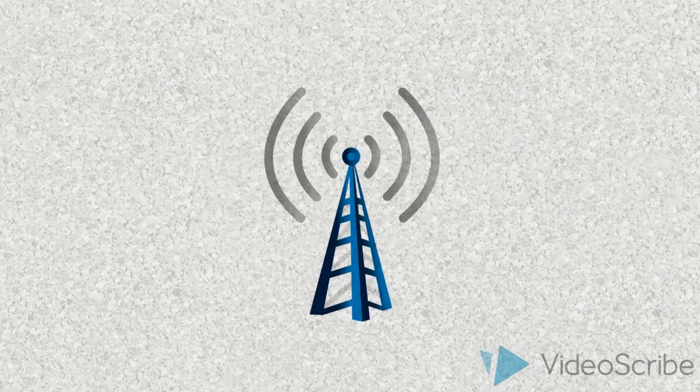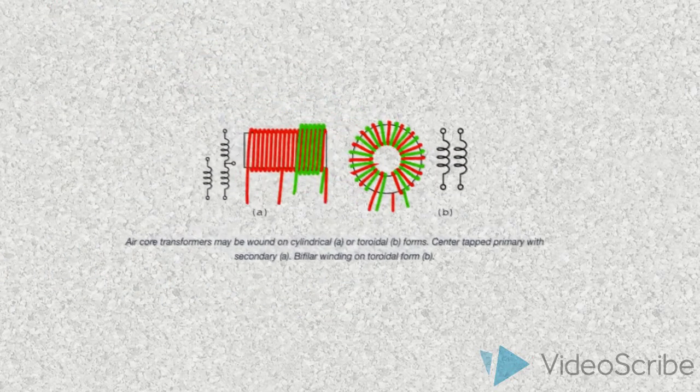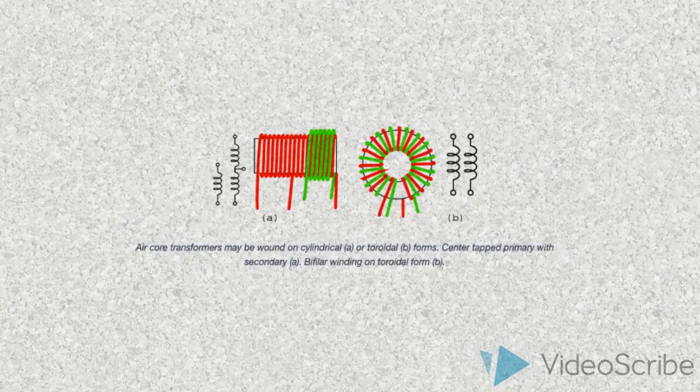Also, radio frequency circuits, which are needed for telecommunications, use air core transformers, as they have windings wrapped around a hollow tube, as the picture shows. Radio transformers have tapped windings, or two or more windings, designed to transfer radio frequency energy from one circuit to another by means of a magnetic field. This transformer may have an air core or some form of ferrite core.